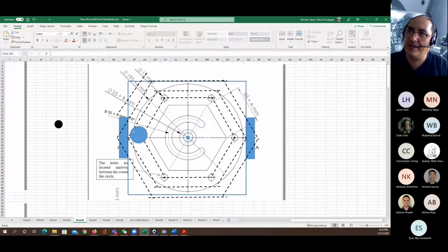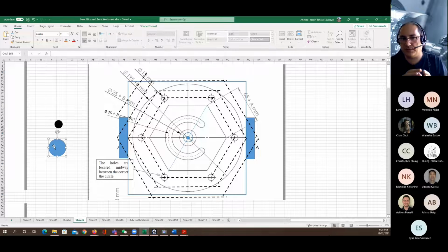That means I will go back once again to here and cut the lines around, then cut another 2 millimeters. You may make the Z to be -4 and do the second cut, third cut, and so on. Then again repeat once more and the final time for the finishing cut of Z equal to -5. Now, before I write down the code for the first step, we're going to find the points for the intersection points. And I'm going to show you how simple it's going to be.